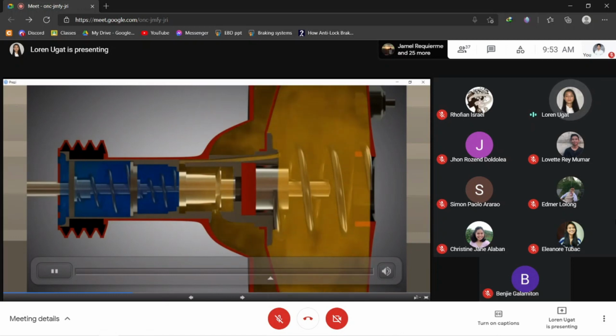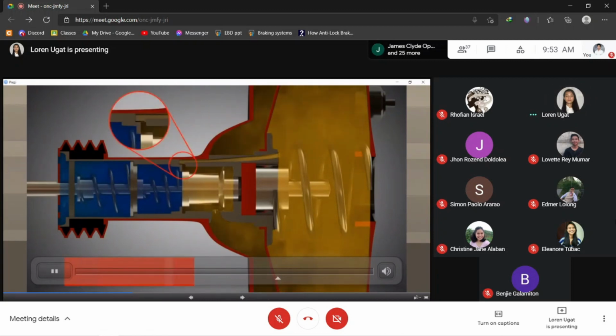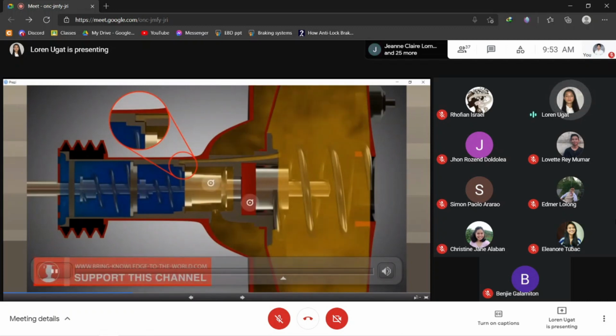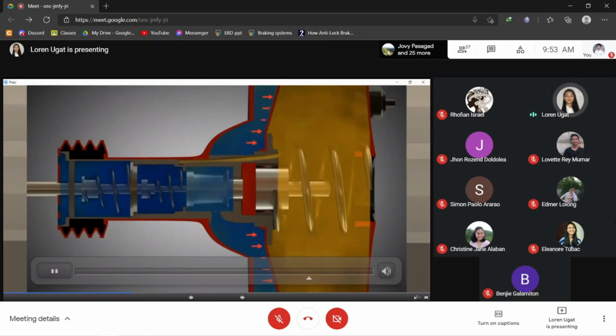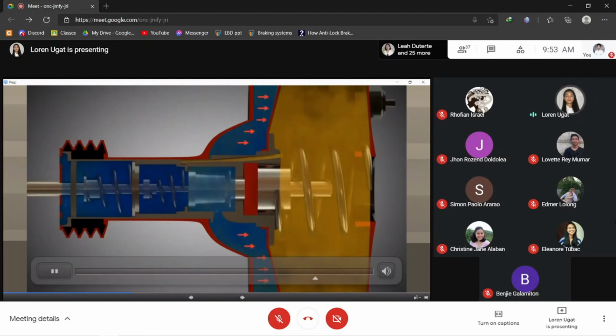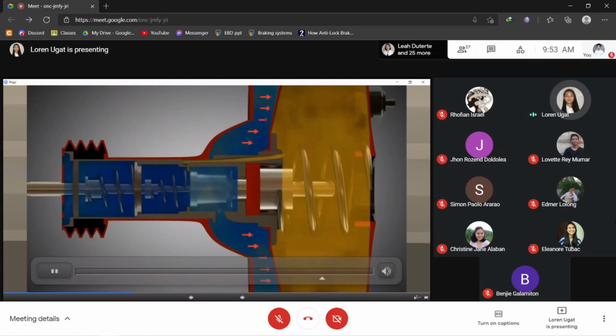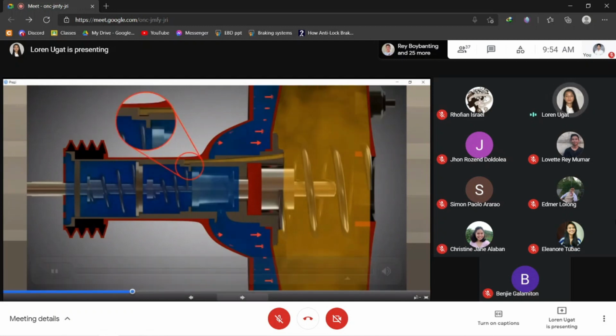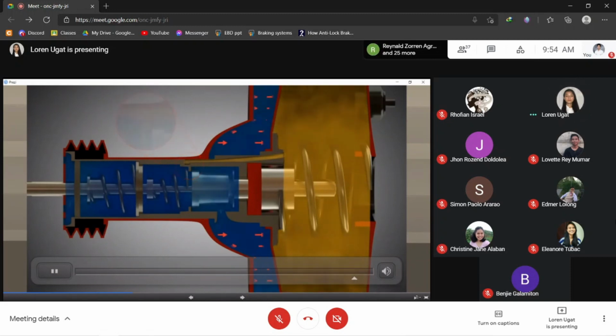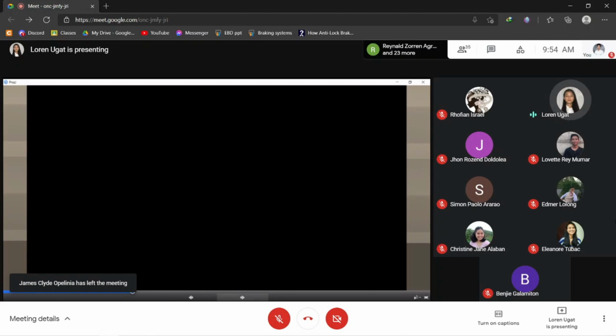As soon as the driver depresses the brake pedal, the poppet valve separates the chambers from each other. The valve piston then presses on the rubber reaction disc that is between the front part of the control housing and the pressure chamber. This creates atmospheric pressure in the pressure chamber. The pressure difference between the two chambers increases the braking force until the driver does not move the brake pedal further forward. Finally, the poppet valve disconnects the front part of the control housing from the pressure chamber. During full braking, the connection between the front part of the control housing and the pressure chamber is permanently kept open. Pressure is constantly exerted on the rubber reaction disc. The atmospheric pressure exerts its full force on the diaphragm.